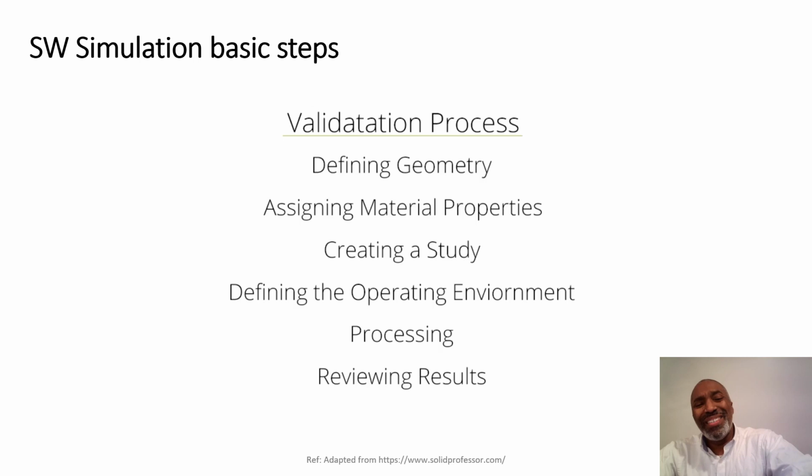Those material properties then are really tied to the types of analyses we're going to do. If we're just going to look at a structural material, and it's a static material, meaning we don't deal with time dependence, really all we're going to need is some sort of modulus, especially if we're just looking at it in a small deformation or linear range. If we're going to take this thing to failure, we want to know when it fails and what it looks like when it fails, then maybe we have to introduce a yield stress so that we can mark off when that happens.